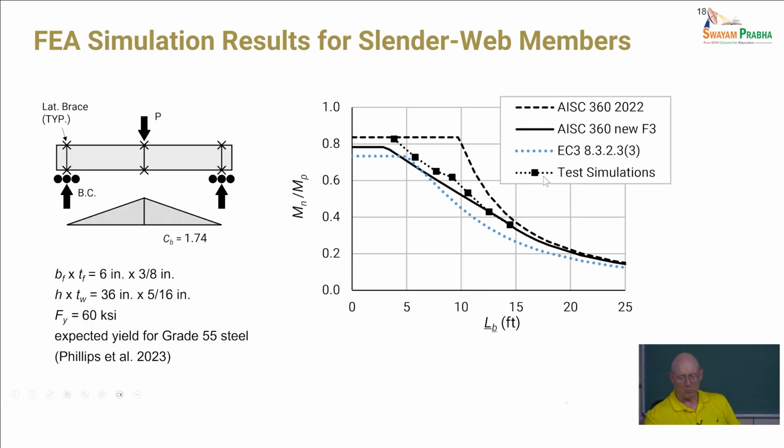If we're in this range where we're starting to scale the elastic buckling resistance above a level where we would anticipate some onset of yielding in the section. And you can see the black curve there. That's the new Section F3 provisions for this particular case.